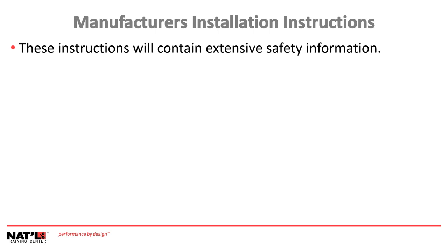Now we'll look at some of the requirements of the manufacturer's installation instructions. All personnel working with DC systems must be properly trained. All personnel working with DC systems must have knowledge of and understand the manufacturer's installation instructions. The battery contains acid or caustic, and the technician must avoid contact with skin, eyes, or clothing. You must have reviewed your SDS or safety data sheet.